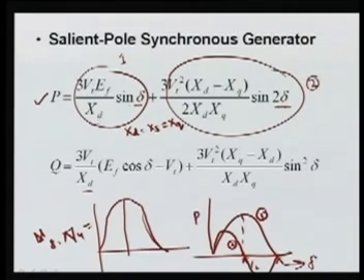This expression is generalized. From it we can get the wound rotor case by putting Xd equal to Xs equal to Xq, and then this term vanishes. This component has double the frequency of the first component, and the resultant is added together and tilted. So this is your real power.